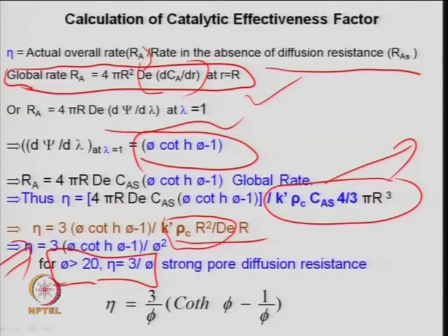And vice versa will be the second case, that is when phi is very small, then eta will approach 1, but eta cannot be 3. So, basically the phi definition in that case is just R by 3 under root k by D. There are different definitions which are available. So, depending upon that value, when this phi value is very low, eta approaches unity, rather than saying 3.